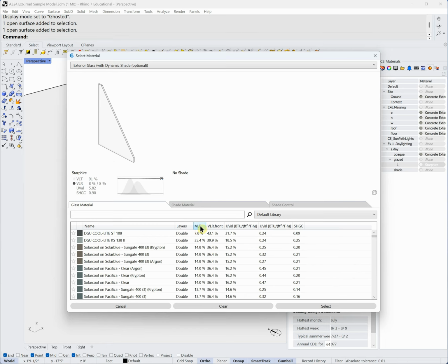All we're interested in is the visible transmittance because we're talking about daylight. And we've talked about this before. Hopefully you definitely should know what solar heat gain coefficient is because we've done exercises in Climate Studio with it and covered it in some detail in several lectures. We can have a solar heat gain coefficient that's high or low compared to a visible transmittance. That's the whole point, or that's a really cool thing we can do with glazing now, is that we have these custom glazing packages we can order, and we can custom design the performance.